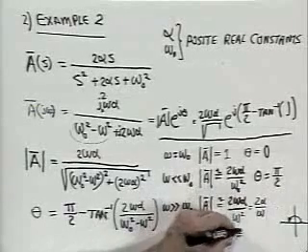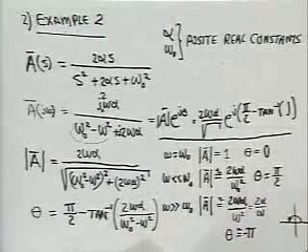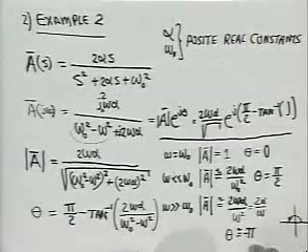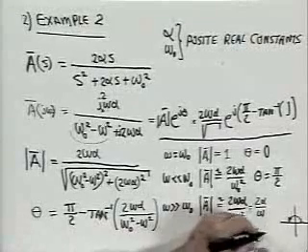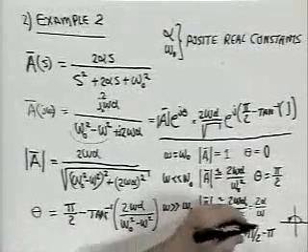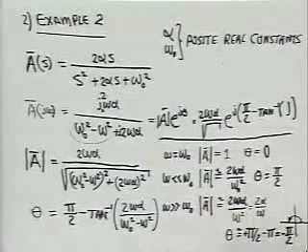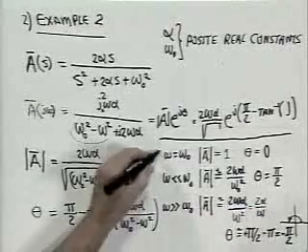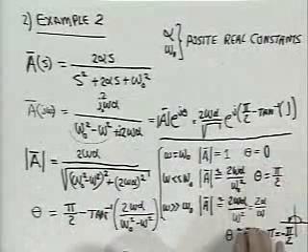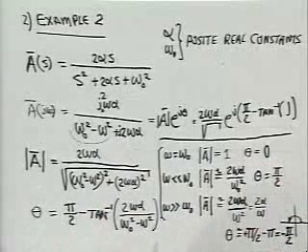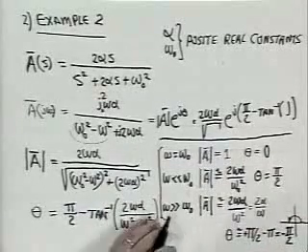So it is approximately minus pi. Coming around like that, minus pi. So, I'm sorry, this is not the whole story. This is just this value. So it's plus pi over 2 minus pi, or it's equal to minus pi over 2. All right, so we've got now asymptotes for this magnitude function and asymptotes for the frequency in 2 different frequency ranges and at 1 fixed point. Let's see how we would plot that.